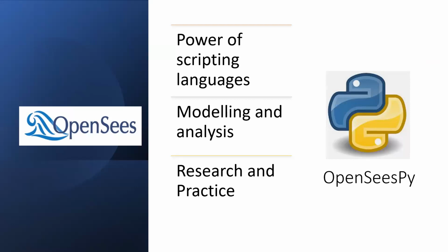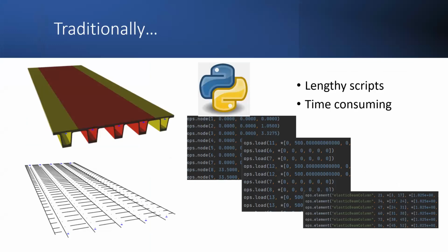So one of the gaps we saw, for our own research purposes, was that we want to do grillage modeling extensively and parametrically, so that we want to produce perhaps 100 grillages and run live load models over 100 grillages. Now, to do that in commercial software would be, well, basically impossible. And so getting into this space of scripting a grillage modeling capability is what the need was for us.